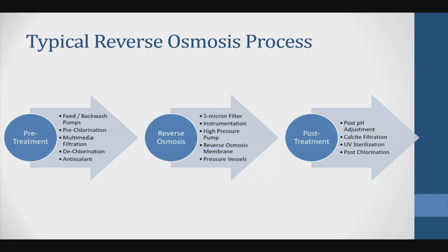We cannot feed high suspended solids to the membranes. That's going to foul the membrane. Now, suspended solids is measured in milligram per liter or parts per million. Before the media filter, we should not go higher than 20 to 30 milligram per liter. So after that, it's going to be acceptable to the reverse osmosis after the media filter.